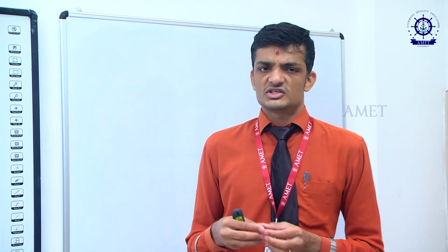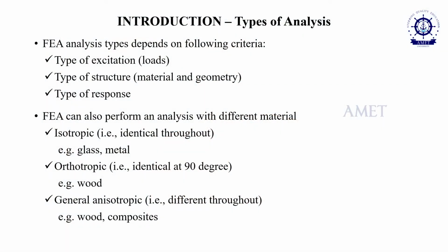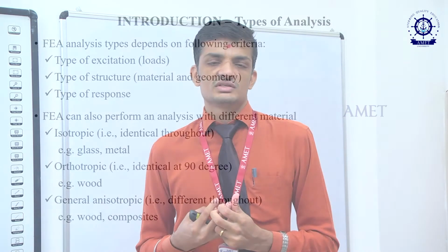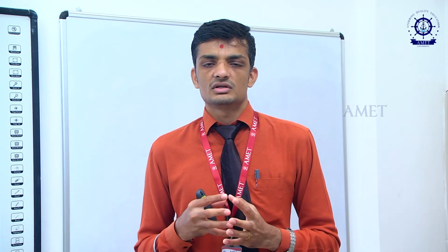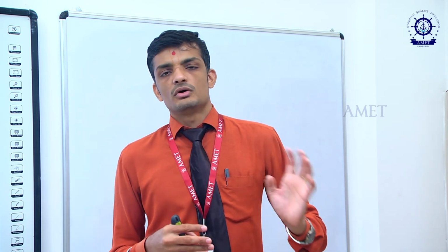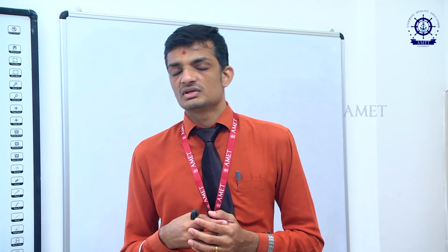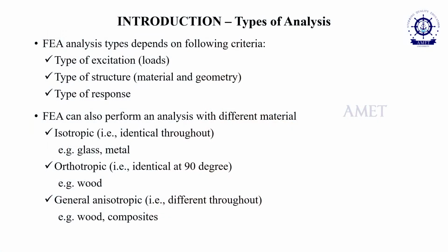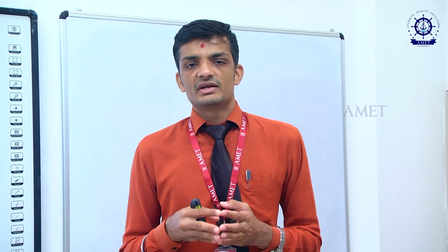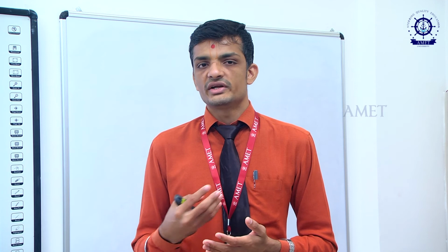And the third category is the response. When you apply the load, the body gives the reactions or the body responds to it. So what sort of response it is going to be, that little bit of understanding is important, because without that you might face issues like how do I manage the conditions, loads, types of support. Say for example a cantilever beam, when you apply the load, the body is going to deflect. The fixed end is not going to deflect, whereas at the free end there will be deflection. The maximum deflection will come at the free end, and after that you are going to interpret the results, right? So if you have an understanding about what type of response it's going to give, then it gives a clear idea. As we discussed, the different types of response are based on the different domains: fluid, solid or thermal.